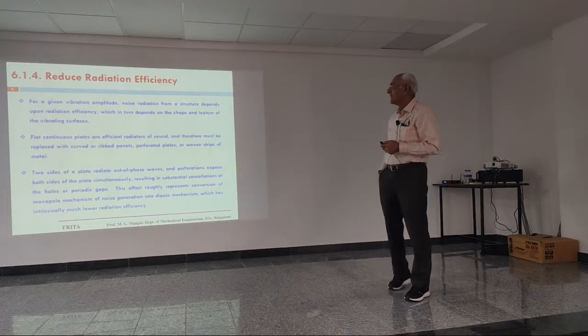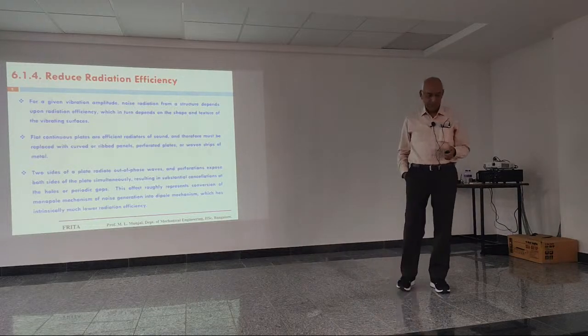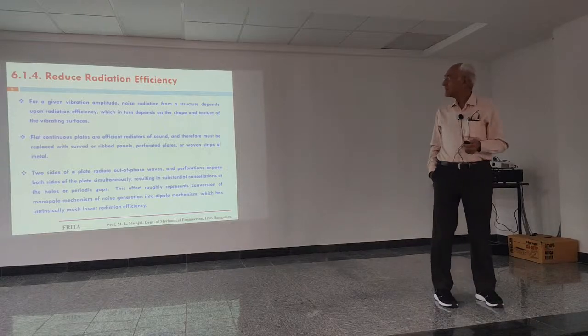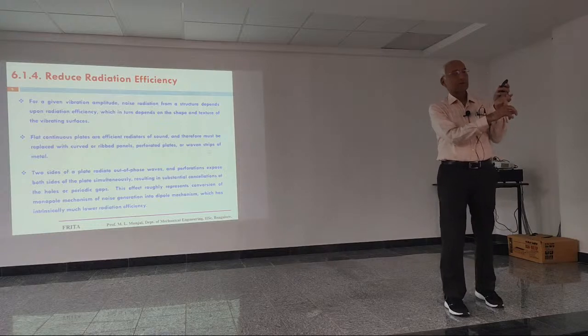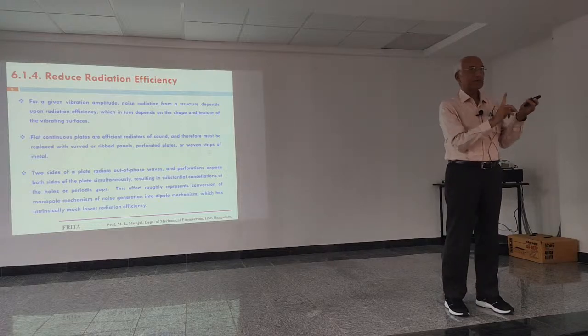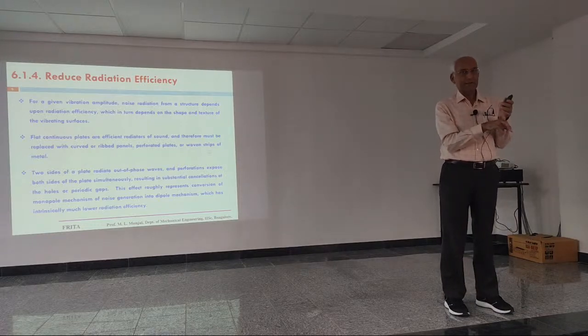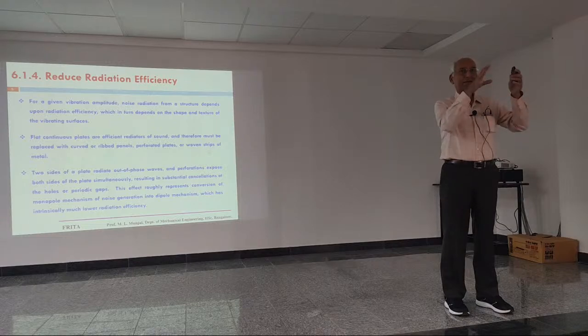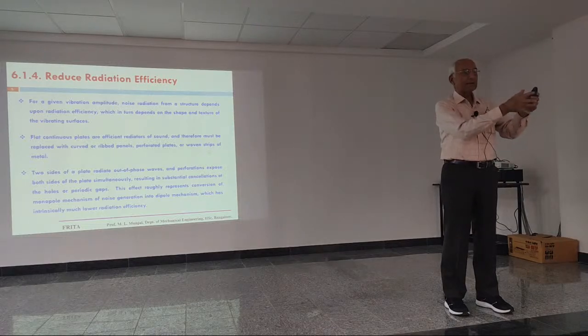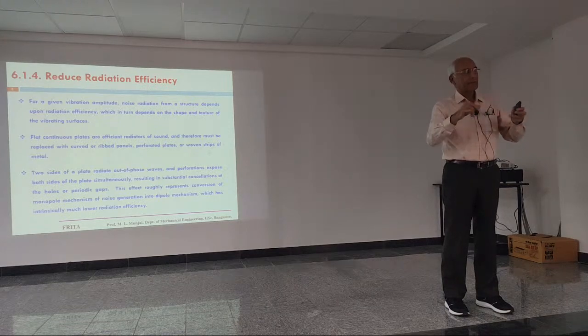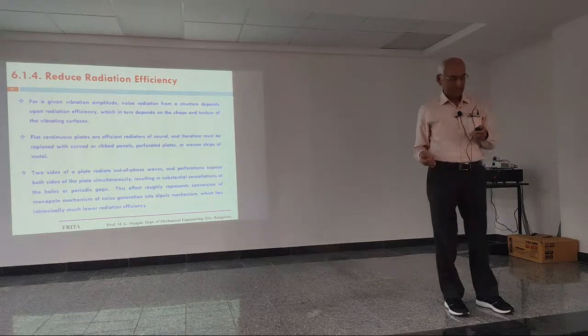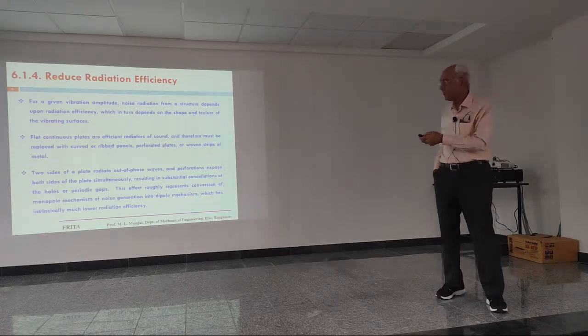Okay. The next thing I was telling you, that I said, reduce radiation efficiency. That means, first thing is, of course, we should make sure that vibration does not take place. Second is, if vibration is taking place, then you design that plate, or whatever is radiating noise, in such a way that radiation efficiency is less and the noise is less. Let's see how we can do it.